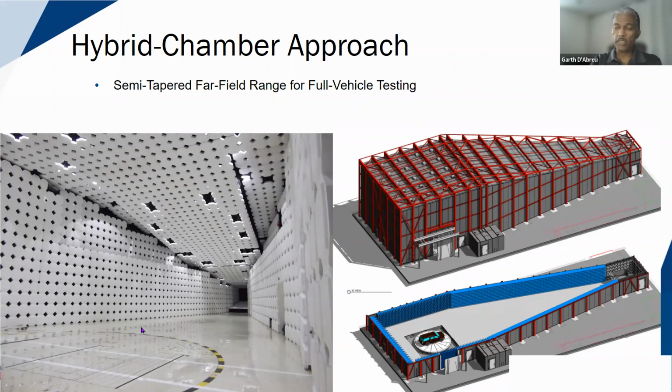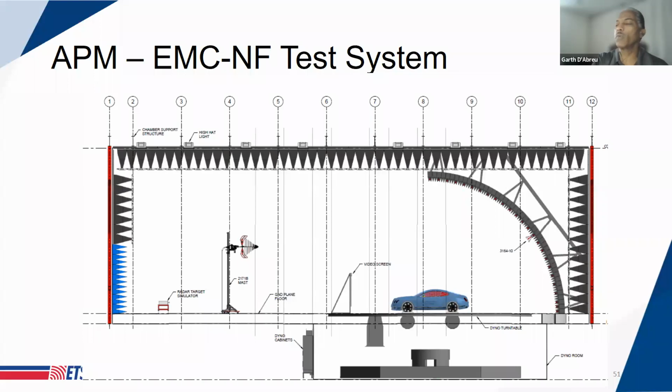And with the limited ability to rotate the vehicle under test in more than one axis, this is quite useful for just doing single axis or single cut antenna pattern type measurements. Again, another one of the compromises where you're bringing techniques that are used for traditional antenna type measurements and trying to adapt those for cases where you have antennas mounted on different structures.